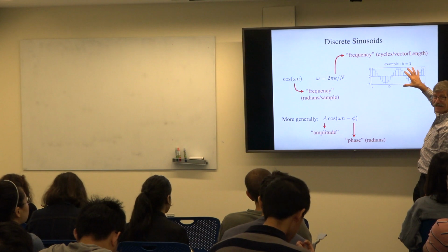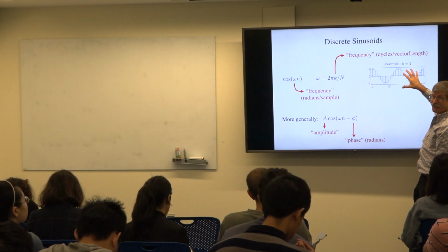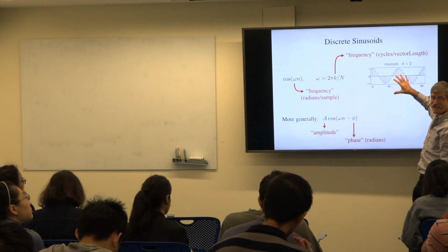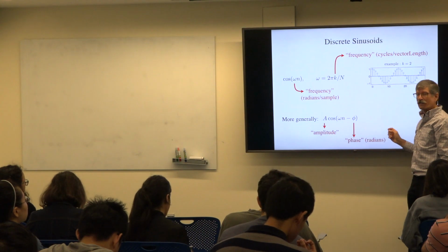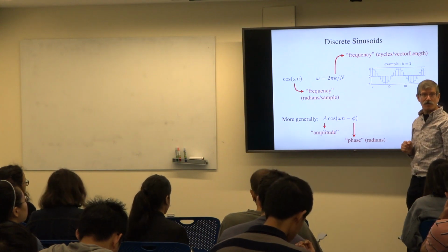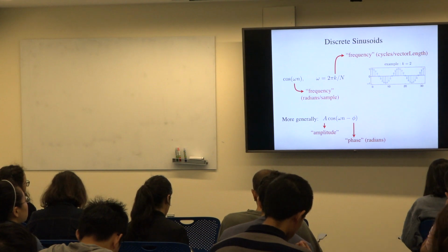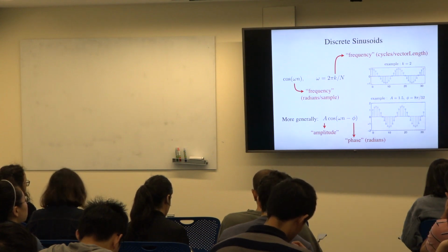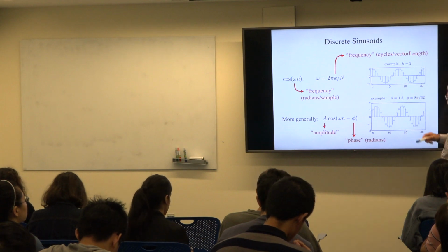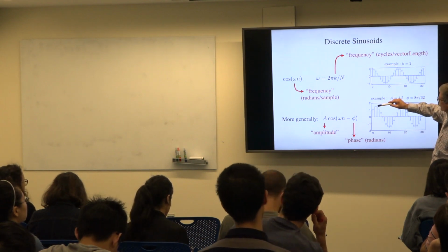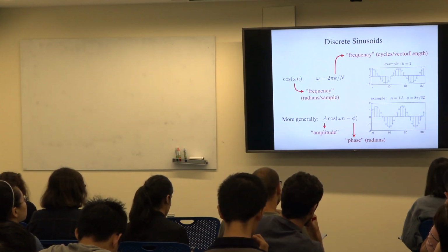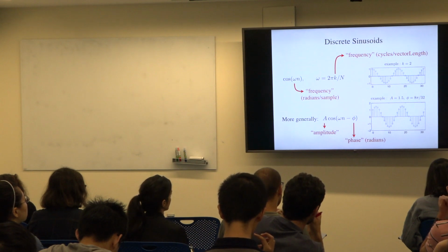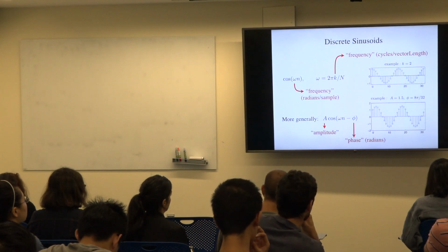Why do you think I'm interested in shifts? We're talking about shift-invariant systems. So shifts are obviously relevant, and this is a shift in radians terms, so it's called a phase shift because it's the phase of the wave that we're going to shift by. Okay, so this is your standard notation for it, so what does it do? Suppose I have A be 1.5. It means that the peak is no longer 1, the peak is 1.5. Suppose that phi is 8 pi over 32. So that's in radians. It's a quarter of pi. Pi is 180 degrees, so I'm shifting by 45 degrees.